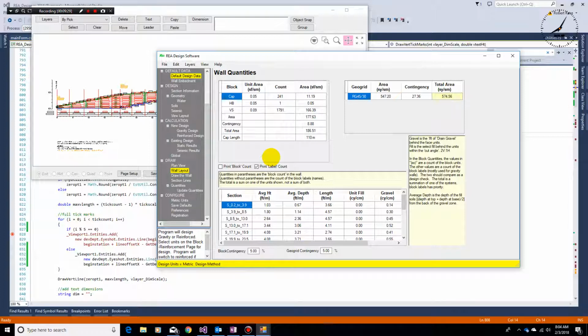The rest of this week I'm going to work on the millimeter to get that working. What we do here in the Imperial units, we input the data always in feet, and then when we go to the AutoCAD drawing, we have the option of drawing in inches or drawing in feet. And the default units in AutoCAD are inches. And then when we print out in architectural or engineering units, it converts it to feet plus inches.